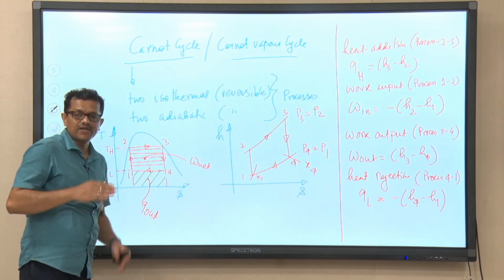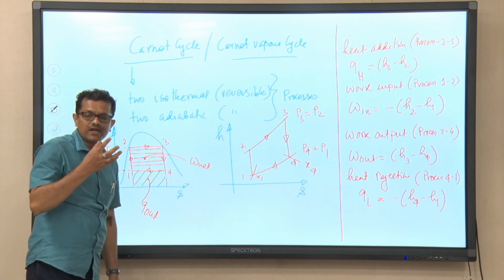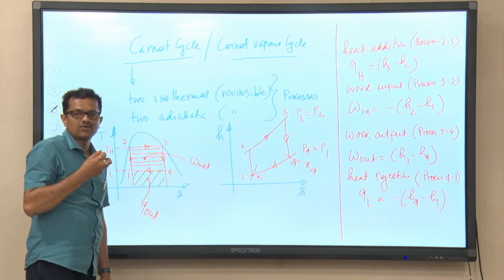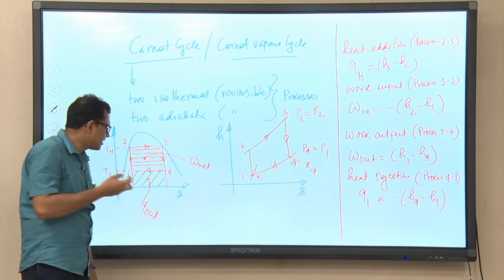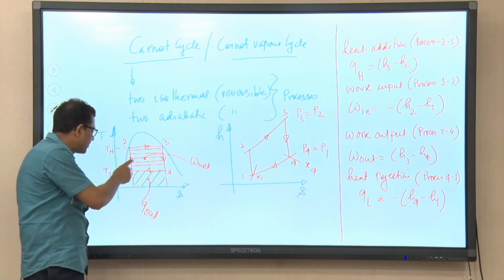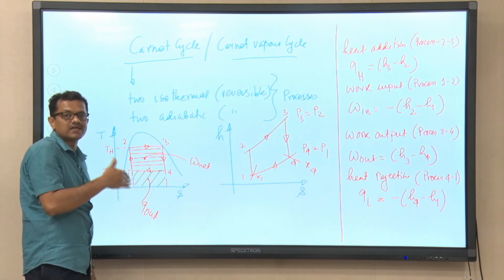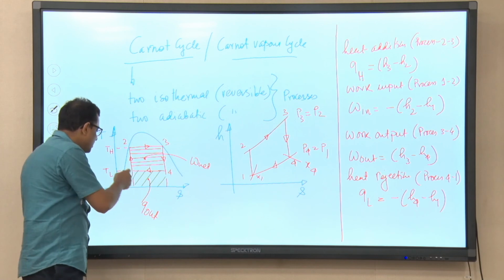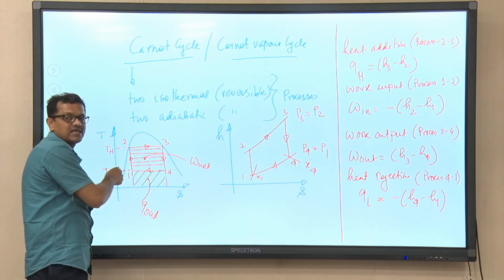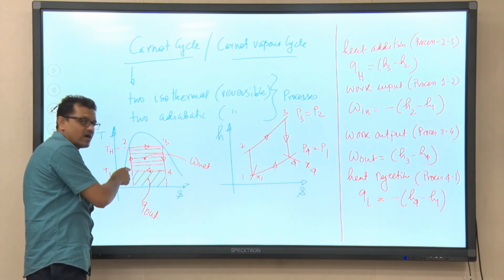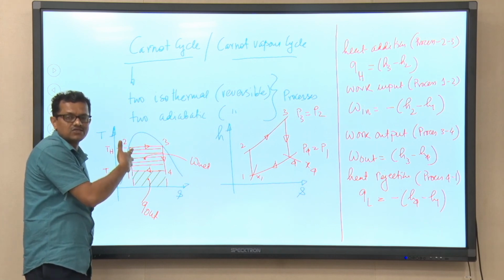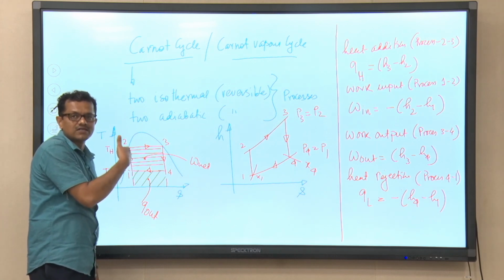It is very difficult to control the amount of heat taken away in this process so that the condensation process terminates at point 1, and that is called partial condensation. The liquid will not be saturated liquid. So at point 1 it is a two phase mixture, not saturated liquid, and that is partial condensation.